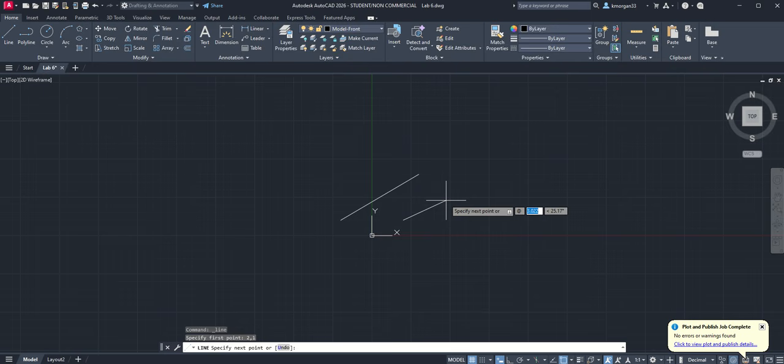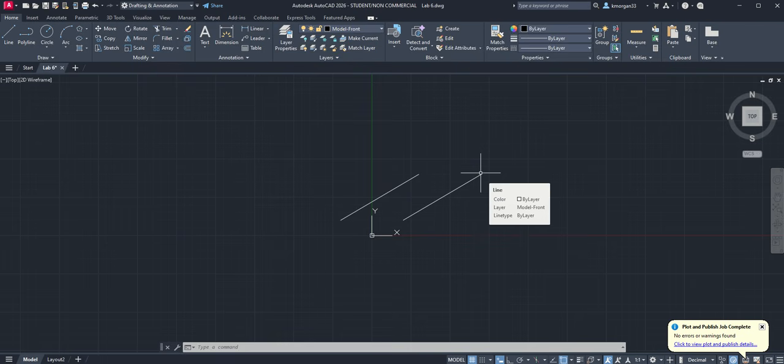And of course I go 5, 3, from there. So now it's going to give me, escape out of it, so you will get the line. So this is different. This point is measured from here, that point is also measured from here, and this point we also measure from there, because we use a pound sign. As soon as you use a little at mark sign, it means that you're measuring from this point. So your 0 is here now, not there anymore.